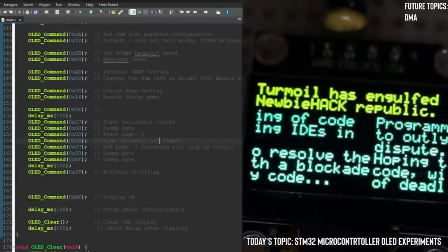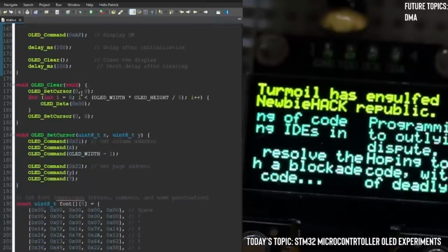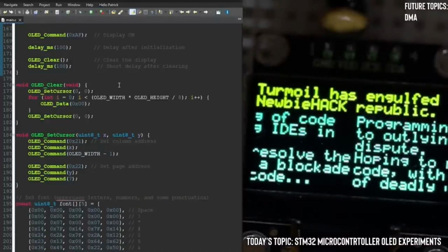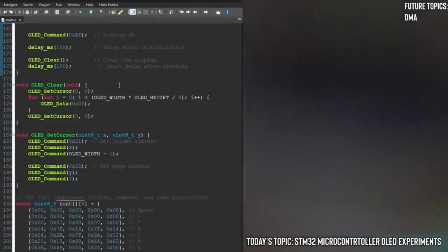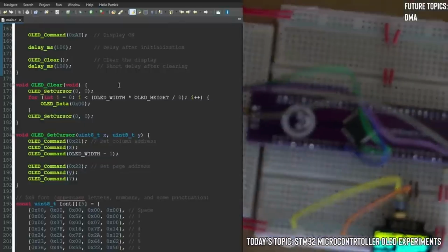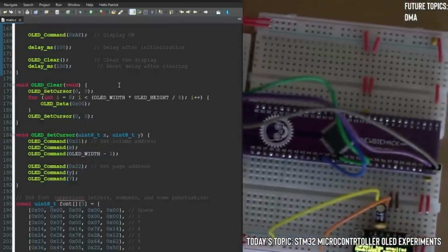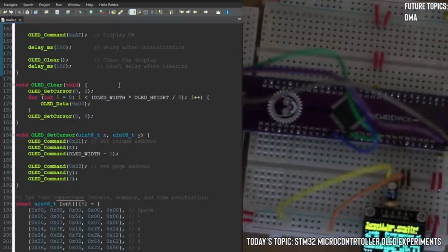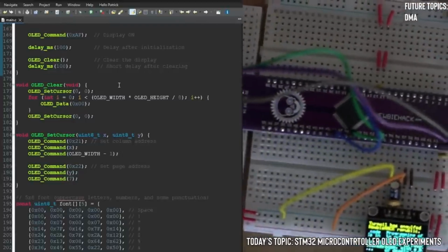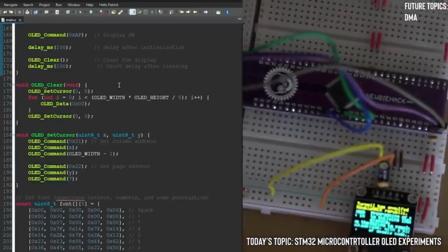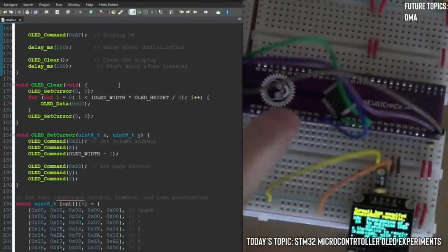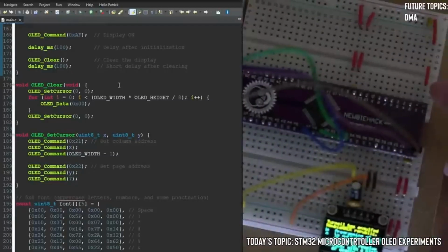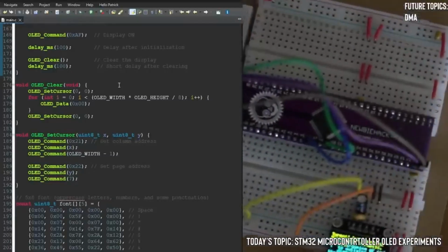We've gone through all the commands, so I guess we could look at the remaining code. My board doesn't have that specifically, no. My board is very minimal. I don't even have the reset pin connected to anything, so I'm not using it in reset mode at all. So you can see it's just the chip, 2 programming lines right here, power, and all the pins that require power are taken to the power rails.